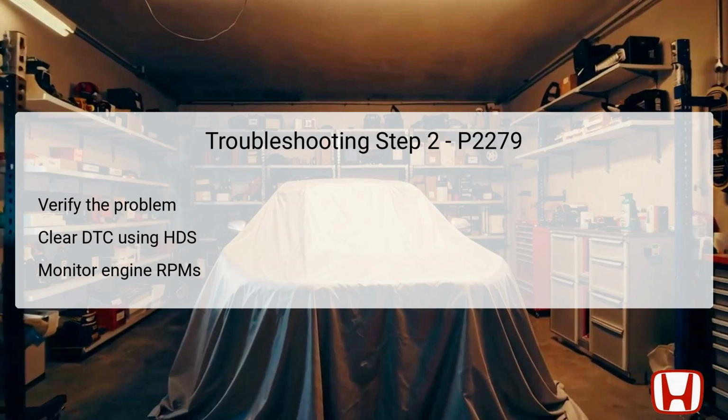Following this, allow the engine to idle for 1 minute. Monitoring the onboard diagnostics OBD status with the HDS for DTC P2279 will determine if the issue persists. If the HDS indicates failure, further inspection is required. Otherwise, if it passes, the system is deemed okay at that moment.